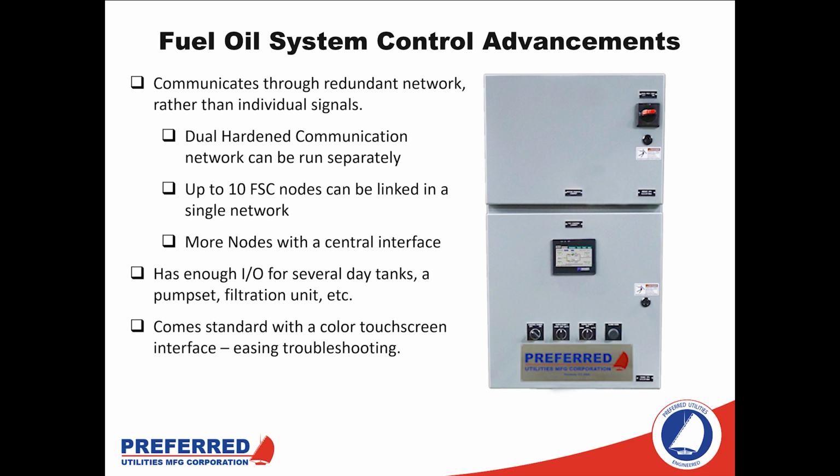Now, this offers many advantages, especially with operator interfaces at each location, where if somebody wants to test the functionality of a day tank, they can remotely operate the transfer pump set from that location and see every other location operating simultaneously through a touchscreen or another interface.